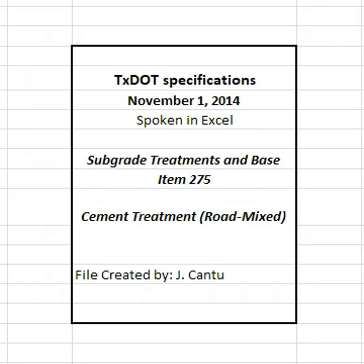Finish grade of constructed subgrade to within 0.1 feet in the cross section and 0.1 feet in 16 feet measured longitudinally. Correct grade deviations of constructed base greater than 1/4 inches in 16 feet measured longitudinally or greater than 1/4 inches over the entire width of the cross section in areas where surfacing is to be placed. Remove excess material, reshape, and roll with a pneumatic tire roller. Correct as directed if material is more than 1/4 inches low. Do not surface patch.